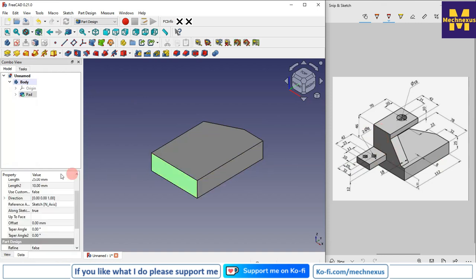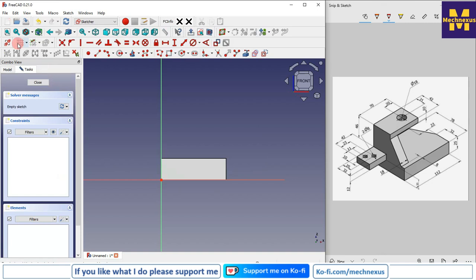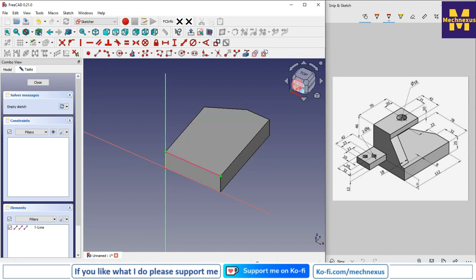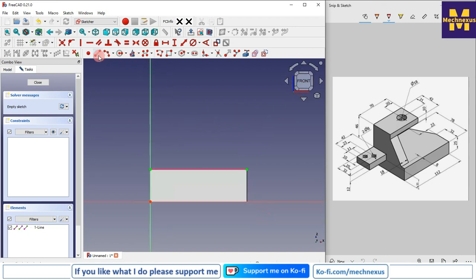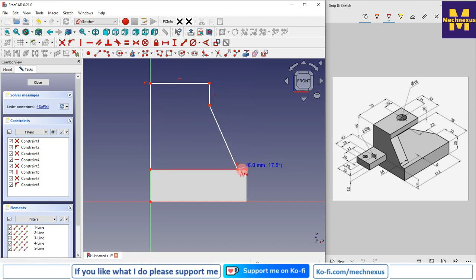And now we will create this profile, and for this we will select this face and click on the sketch, and we will click on the project geometry, and we will select the polyline tool. Here is a polyline. We will create a rough profile and complete the loop. Now give the dimension.